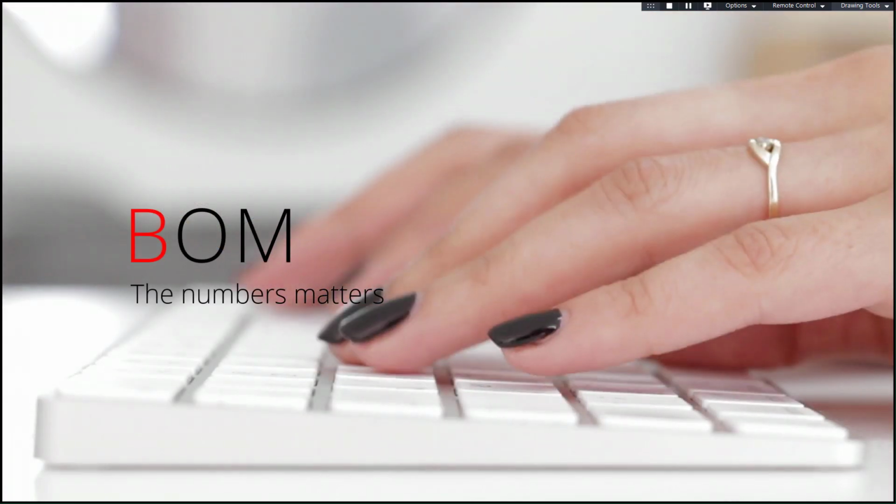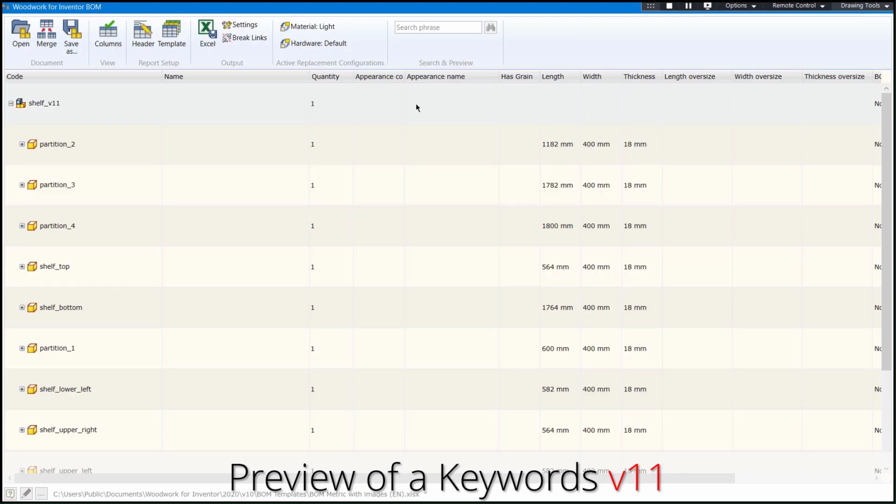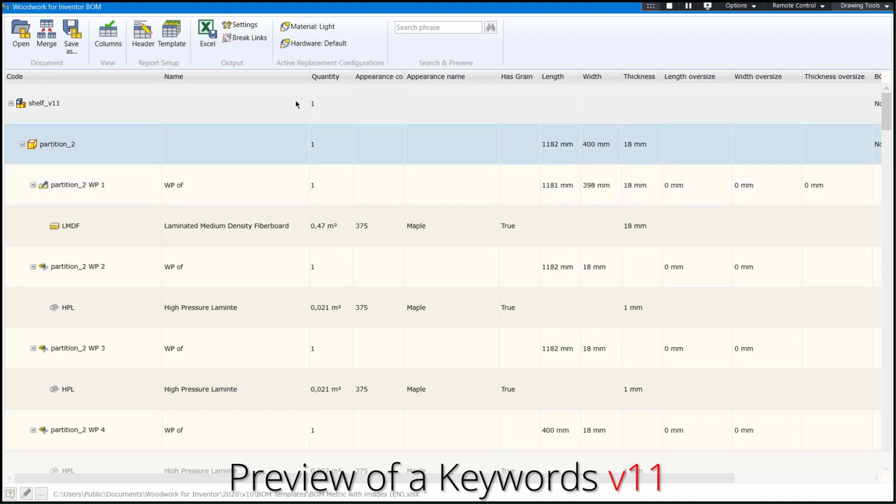Now let's take a look at the BOM. And those of you who work with the BOM templates know that sometimes it's quite difficult to pick the right keyword for a template. It actually defines what kind of data you want to see in your report and where and how you want to process that data. So that's why we have a new keyword preview option in the BOM editor, which allows you to actually see the results of the keyword without actually generating the BOM.